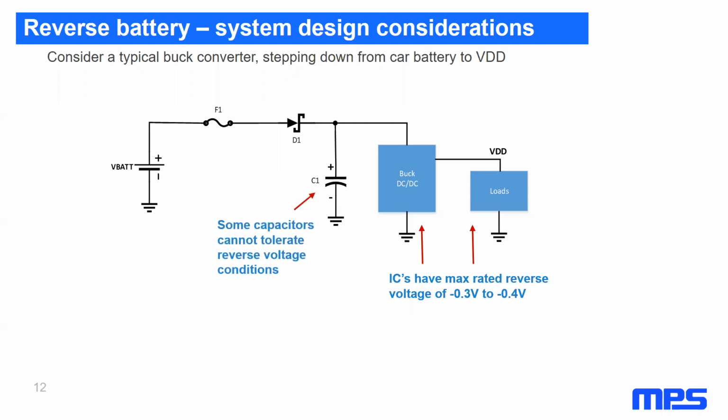Also, other passive components, such as input capacitors, are also sensitive to reverse polarity. While multi-layer ceramic caps can tolerate reverse voltage conditions, other chemistries such as aluminum electrolytic and tantalum electrolytic will not. These types of capacitors can suffer damage or degradation.